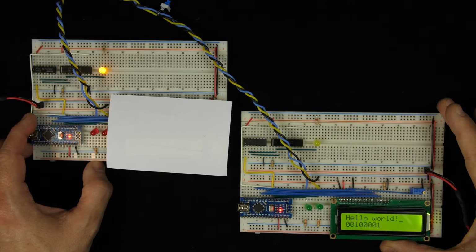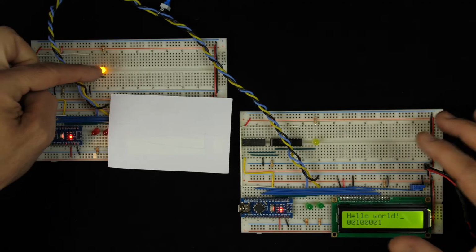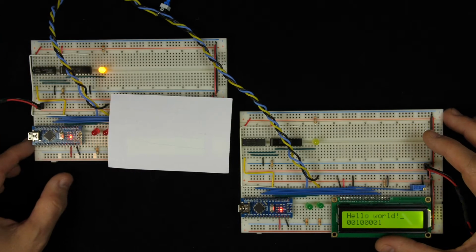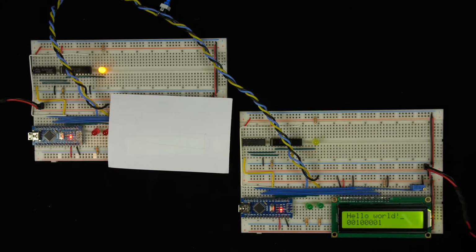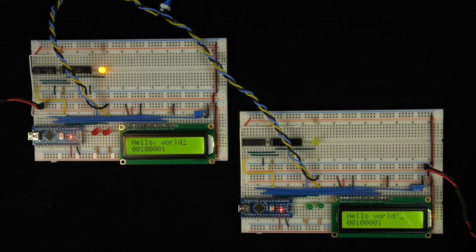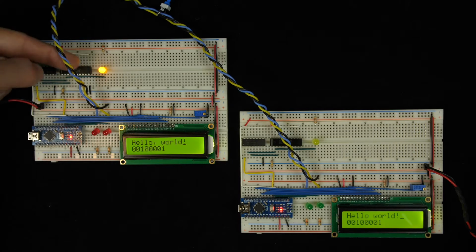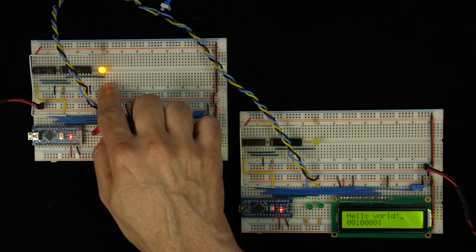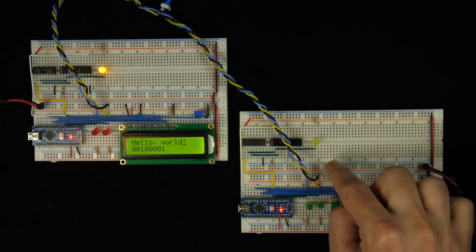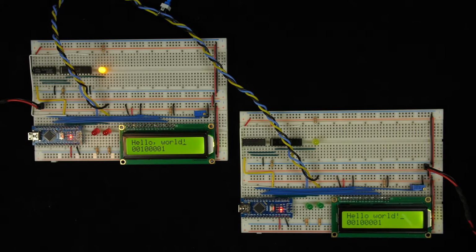But if I show you the parity bit computed by the transmitter, I bet you can tell now. Since the parity of the transmitted message doesn't match the parity of the received message, we can't possibly have received the correct message. But of course, you couldn't know that without knowing what parity the transmitter computed. So the only way this is going to be useful is if the transmitter is able to send its parity bit to the receiver somehow, so the receiver can compare it with its own computation.